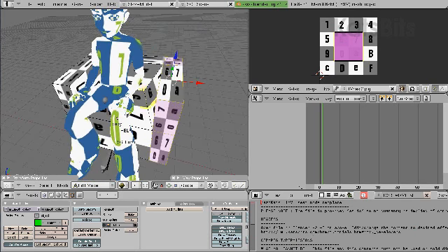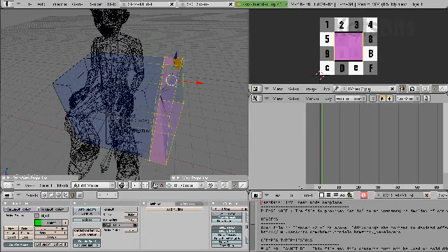As you'll see, we've missed a vertex, so change select mode, Control Tab to vertex, select that vertex in the corner. Because we're in textured mode this might be tricky, so press the Z key twice, which drops us down into wireframe mode.